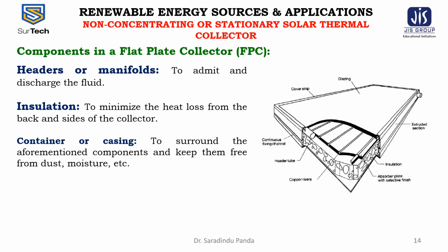Next component is the headers or the manifolds to admit and discharge the fluids. Most flat plate collectors have two horizontal pipes at the top and the bottom called the headers, and many smaller vertical pipes connecting them called the risers. The risers are welded to the thin absorber fins.